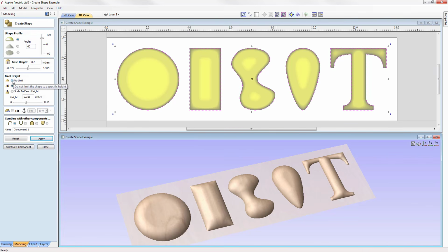Now all of the other shapes are being flattened off. If I put my mouse here you can see the Z shown as 0.315, you can see the rectangle there as well, 0.315, the top of this shape 0.315, and the top of this egg shape here again 0.315, and that's because we've got that entered into our form, so as the shape reaches that value it's flattening off.